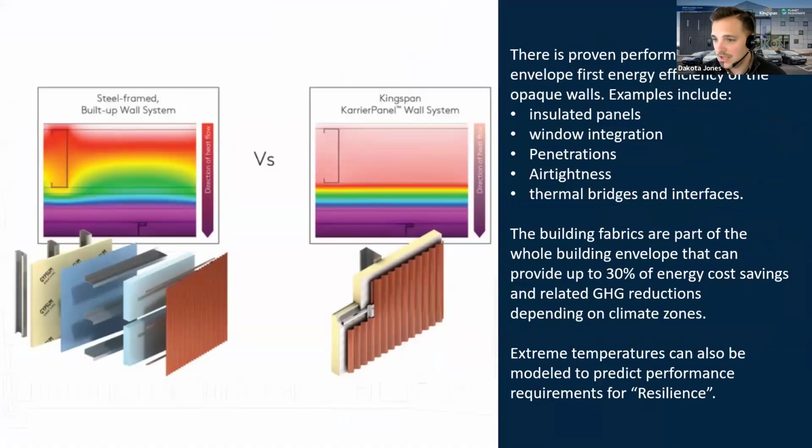If we look at the thermal performance, as far as what we can expect from our envelope, and compare it to a multi-component system, right? Again, we have our trusty, in this case, single skin multi-component system. This is where those darn Z-girts get to rear their ugly heads again, right? Very obvious short circuit through that envelope. You can see the temperature differential throughout there. It's pretty stark. It penetrates very, very deeply.